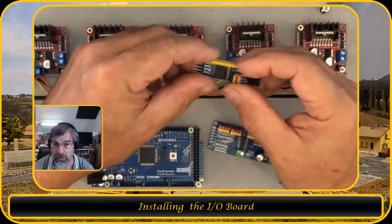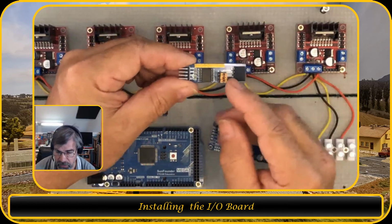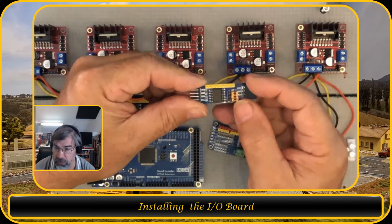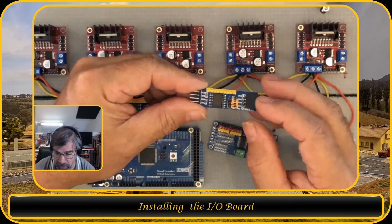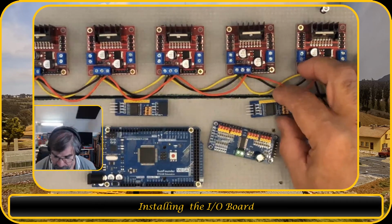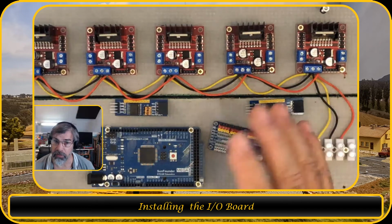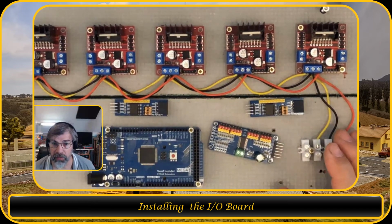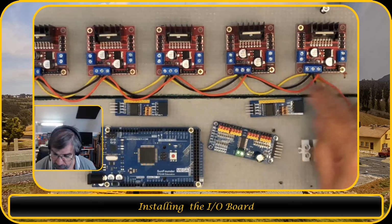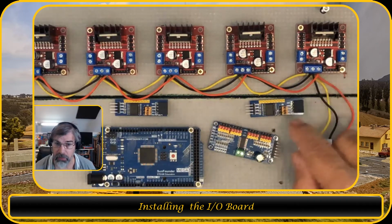With these I/O boards, you need to set the address. So the address will be set with these jumpers, and then I'm gonna address that in the script as well. But first let me take out the DuPont connectors, and I will show you how that wiring is.